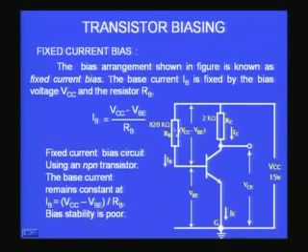Okay. Now what about the VCE? Can I get the value of the VCE? Yes, you can also get the value of VCE and IC from this circuit. This is from the load line, we have already discussed that. 15 volts, you have 2 kilo ohms, there is a voltage drop across 2 kilo ohms, and the balance is available at VCE. So if you measure VCE, you can calculate IC,